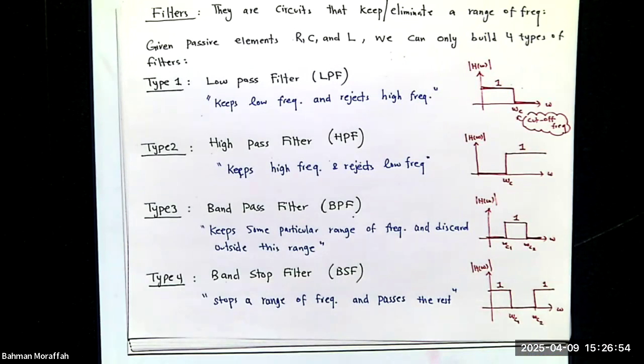Notice over here, I only drew the magnitudes. I didn't draw the phase. In a lot of applications that we're dealing with, the magnitude is the one that's important. And a lot of applications are not sensitive to the phase. For example, your ear is not sensitive to the phase, and it's only sensitive to the magnitude.